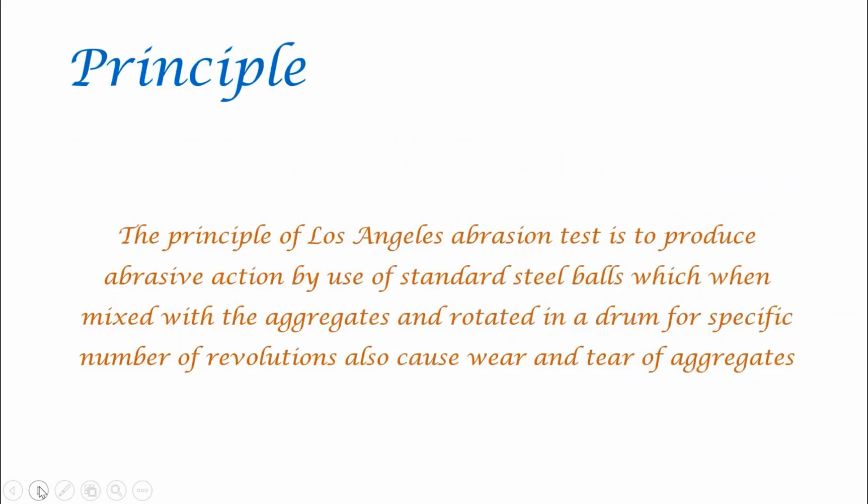The principle behind this test is to produce abrasive action by use of standard steel balls, which when mixed with the aggregate and rotated in a drum for a specific number of revolutions, cause wear and tear similar to that of the road surface.